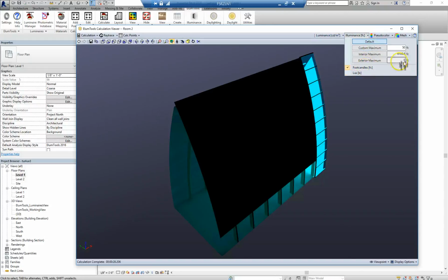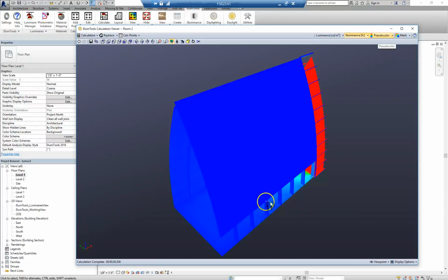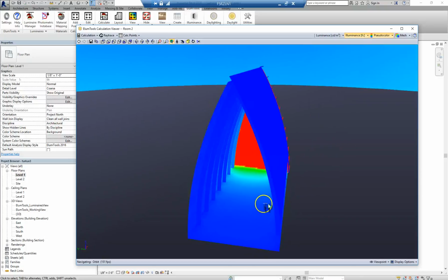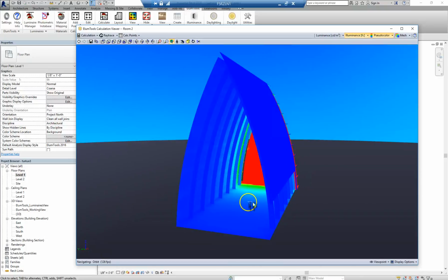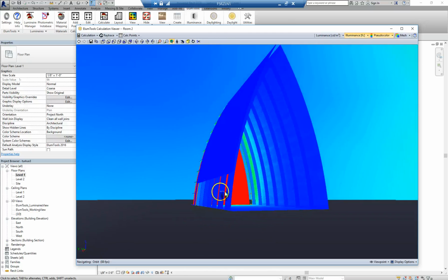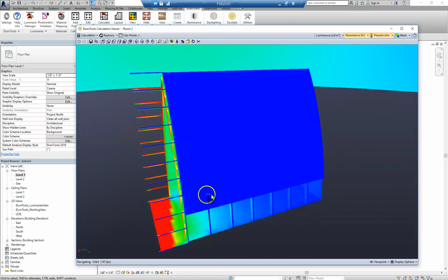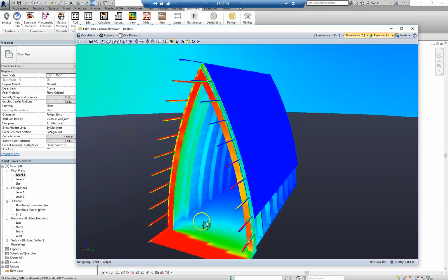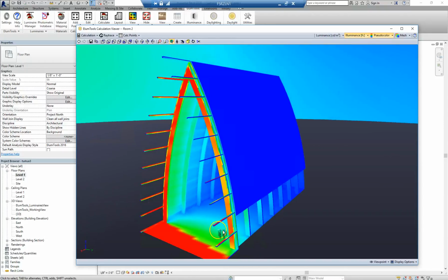And then I'm switching it to foot candles and turning on pseudo color. And then we're going to take a peek inside here. Let's see what we have. Obviously, I did not place any of the point calculations in here, but you can certainly place them on the floor. I'm not sure how excited Elumtools will be if you try and place it on one of these curving walls. It might get a little upset. But play around with it and check the results and make sure that they seem to line up with what you think they need to.